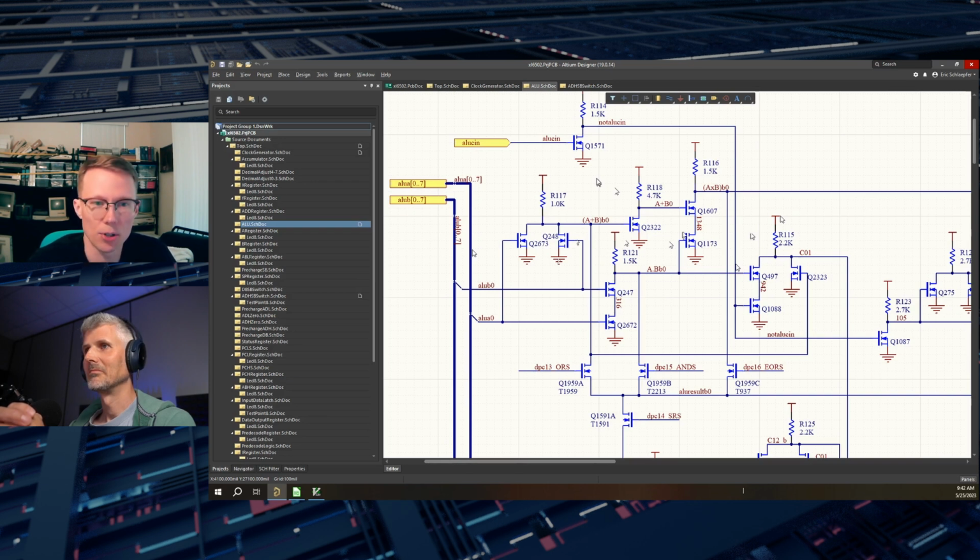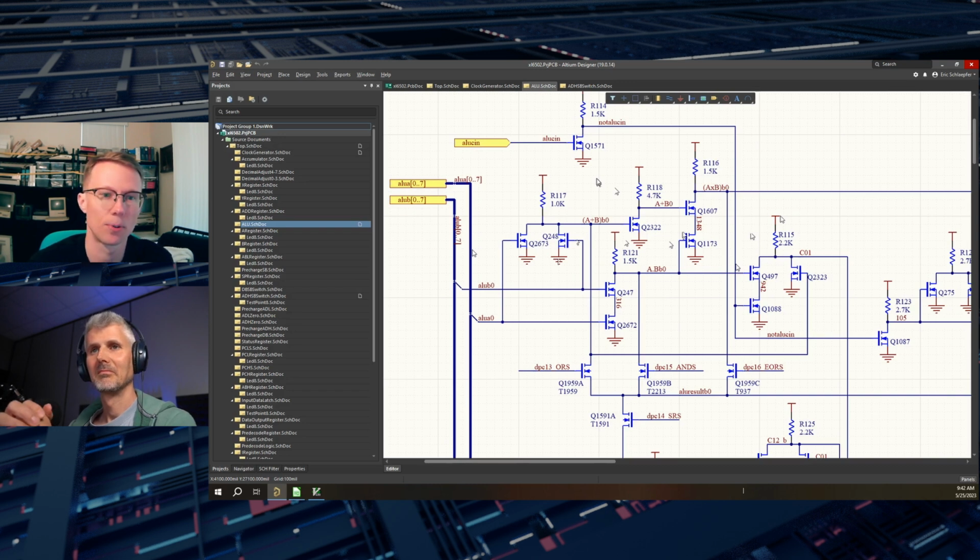So you pre-charge, and then in the next half clock cycle, you selectively ground the bus when you're trying to load zeros onto bus lines. For example, if you look at the RTL, let's say you're transferring a register onto the bus because you're trying to transfer it from one register into another register. In the previous cycle, you've already pre-charged all of your bus connections up to a logic 1. And then in the next cycle, you selectively pull some of those lines down to 0 volts.